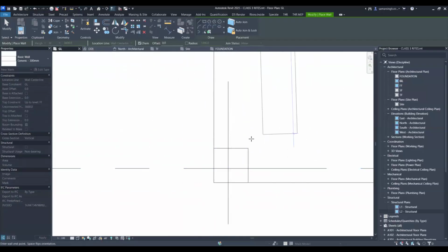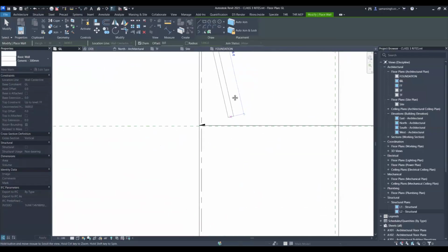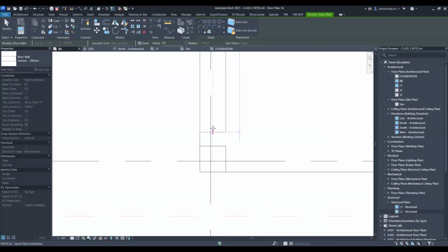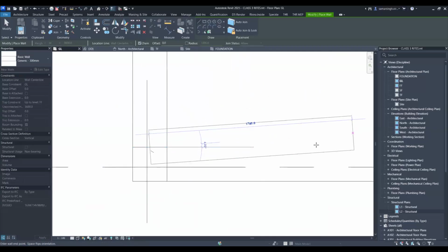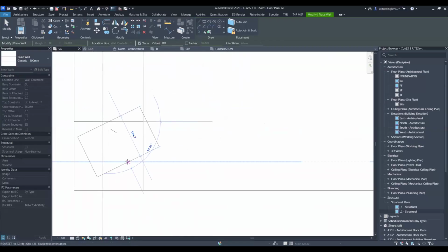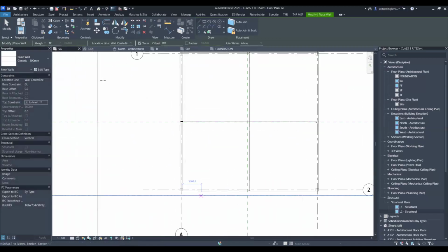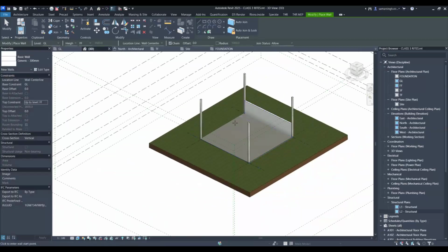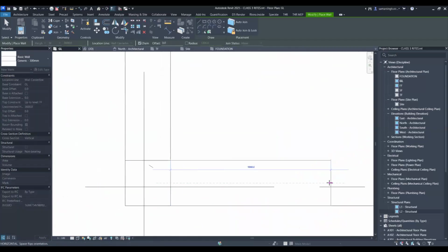So this movement also, if you're using Revit for the first time, it will take a bit for you to learn and move pan with your mouse. But once you get the hang of it, it is quite easy. And here you can see I have connected the wall on the other end. Revit gives us the option to continue making the wall. That can be the case, but for this particular example, you can see I want the wall from here, not from where this is continuing. So I can just press on escape. Going to 3D. Yes, you can see the wall has been made. So let me please continue this process on all the sides.